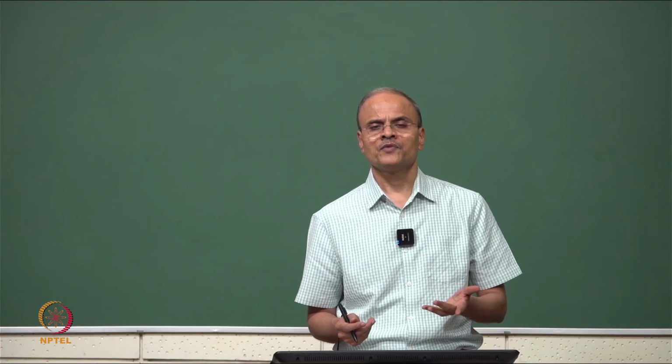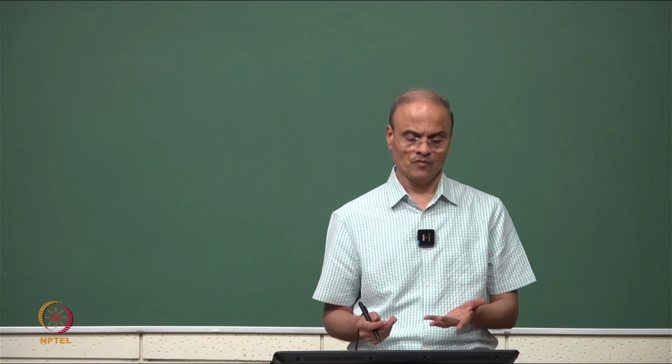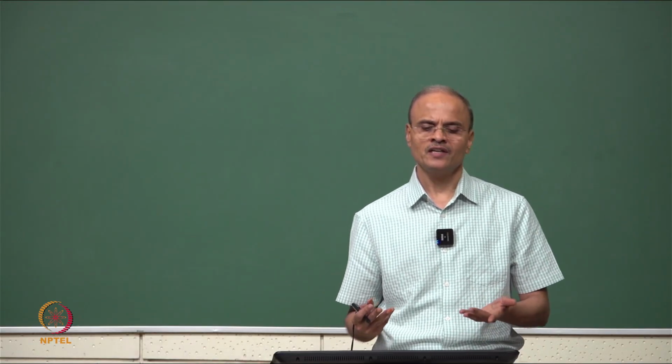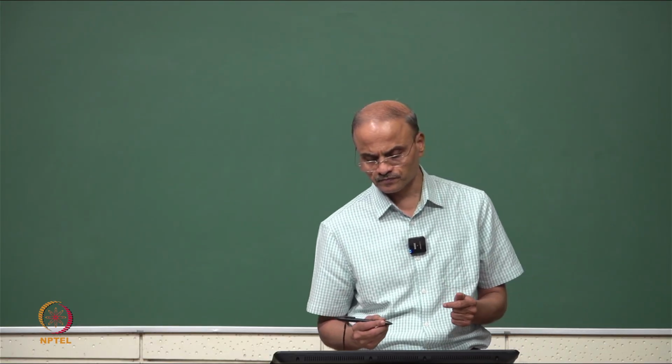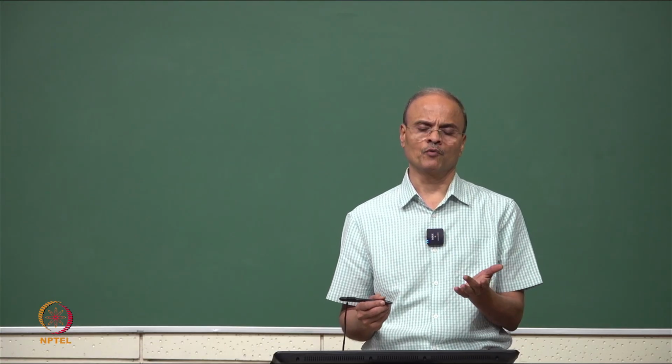We do not require the mass and stiffness description of the structure in this case, right. If the model is there, we can use that to find a response on the structure, and this problem is about basically learning that process. So we also studied in the lecture classes that we can find the frequency response function from the model, right.